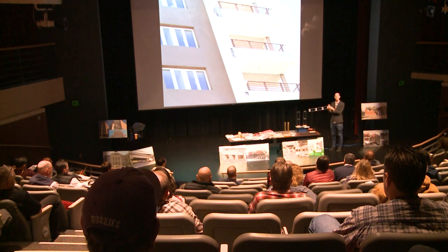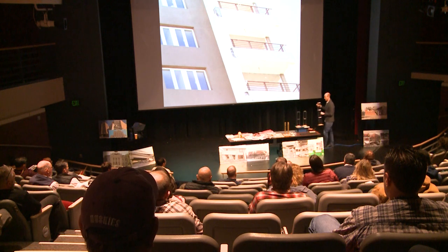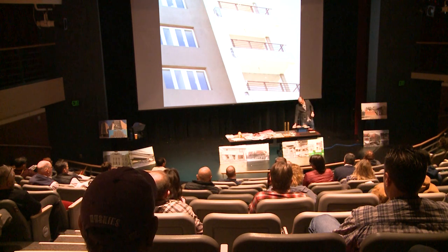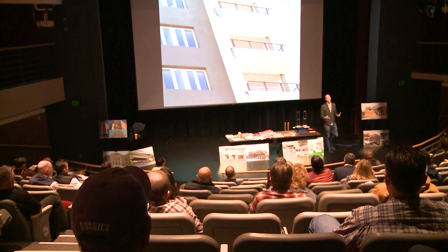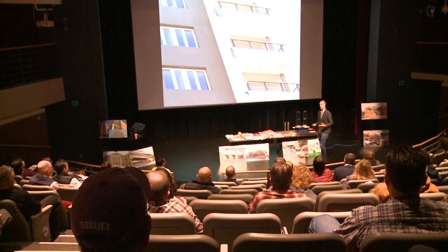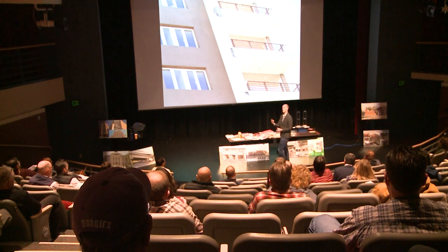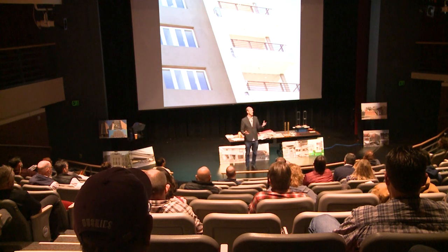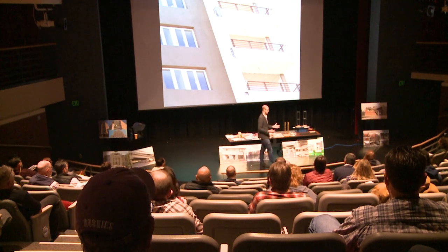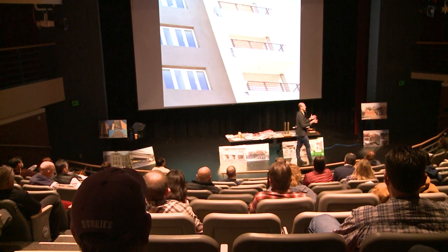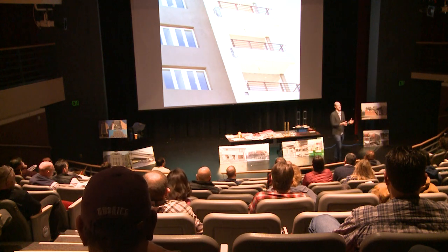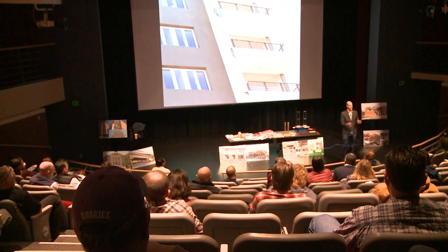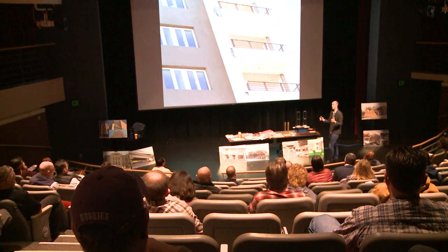Laterally, we have to design the building to do that more or less, even though that was 1 plus G. When we design buildings for gravity, we take the dead load of the building, we multiply it by a factor. We take the live load of the building, so say an office building, as many people as realistically, as much stuff could fit in that based on the design codes, and it's pretty maximized.